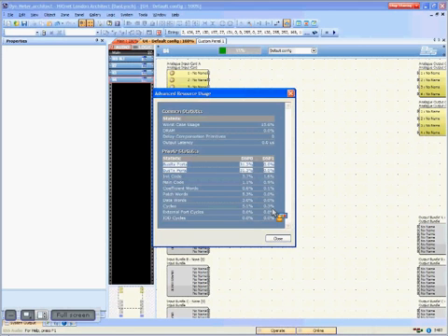However, the Blue 800 has CobraNet and BlueLink. Because BlueLink can grow and shrink, you never know how many ports it's going to need. You have to reserve 32 of those ports ahead of time for the CobraNet module. You also have to reserve some of them ahead of time for the analog ports. Otherwise, BlueLink could gobble them all up. That's why that reads 15%.